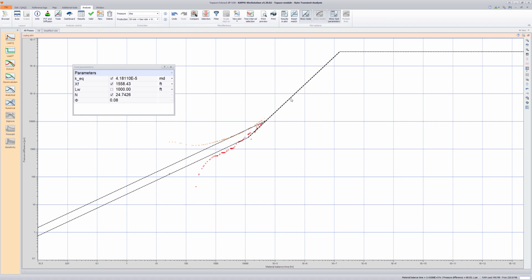Also observe a change in the number of fractures since the fracture half-length is changing to keep the permeability fracture half-length squared product constant. The user has the flexibility to impose any of the parameters by deselecting the box. Here fix the length of the well.